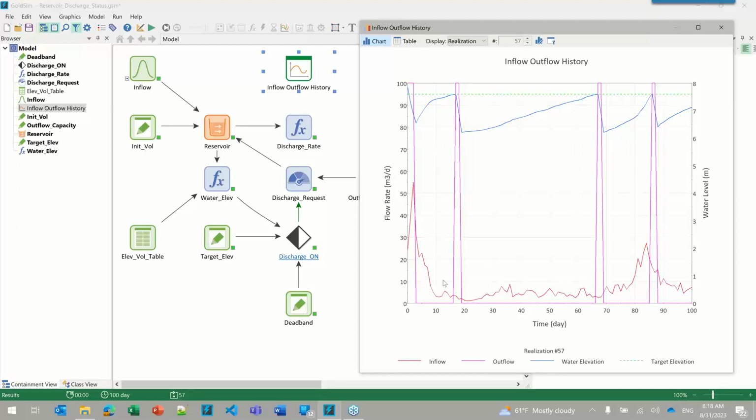Now, this is a simplistic approach because our discharge rate is constant regardless of the water level. And that is something that's not always hydraulically possible, right? So a lot of times you have maybe a weir or an orifice or something where water is flowing through it, and the flows are heavily dependent on the water level.